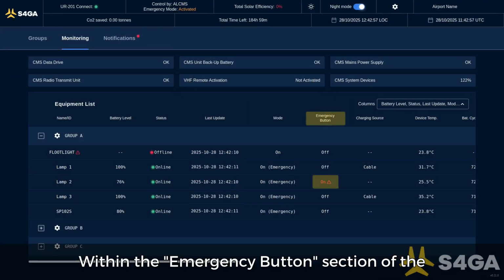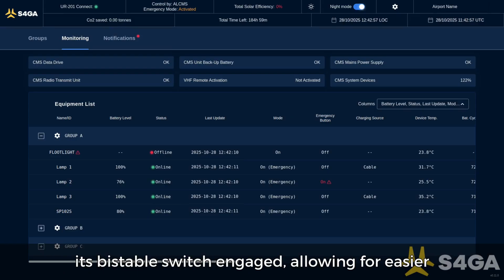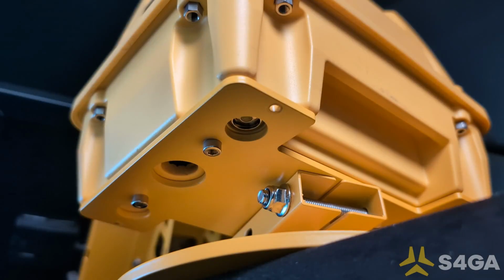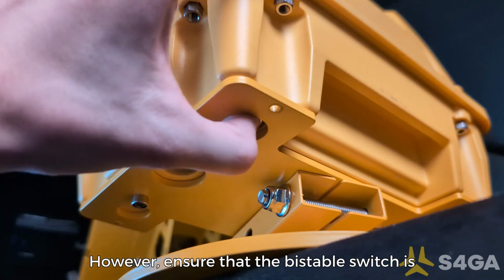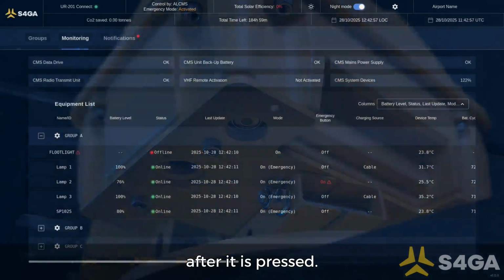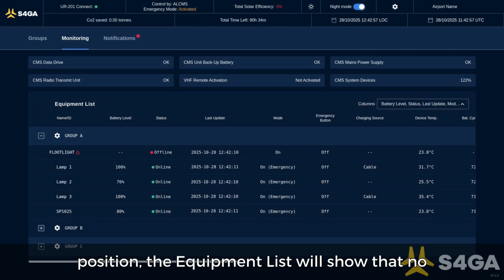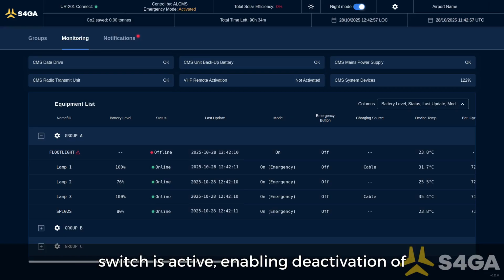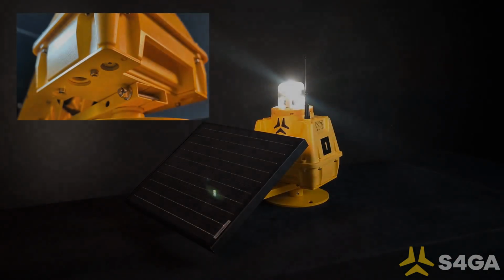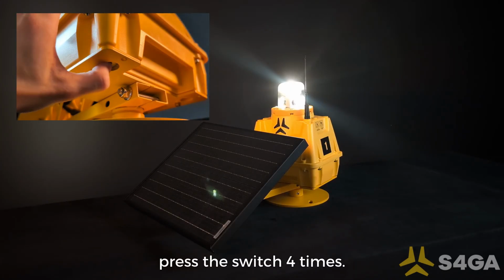Within the emergency button section of the equipment list, you can identify which device has its bistable switch engaged, allowing for easier localization. However, ensure that the bistable switch is returned to its neutral position immediately after it is pressed. After the switch is returned to its neutral position, the equipment list will show that no switch is active, enabling deactivation of emergency mode. To deactivate the monostable emergency switch, press the switch 4 times.